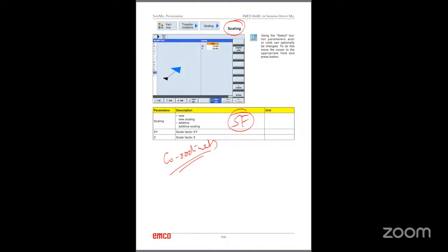So we can manufacture a particular shape, no need to write the program again. By using a proper scale factor, you can machine the same shape, object geometry, in a big size or a small size, but the geometry will be the same.